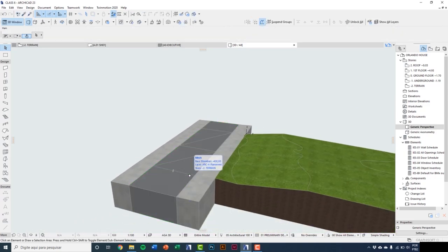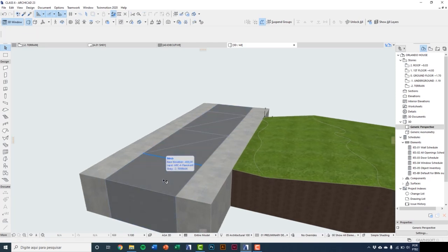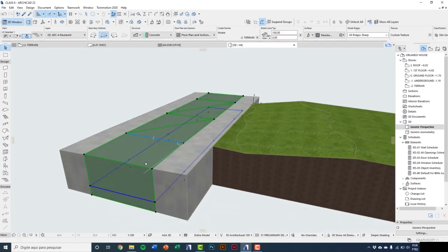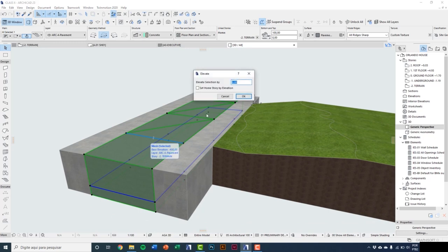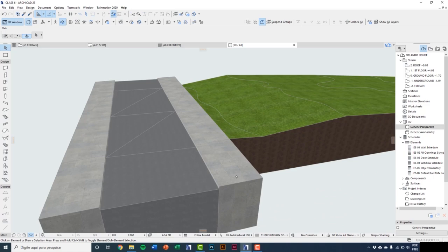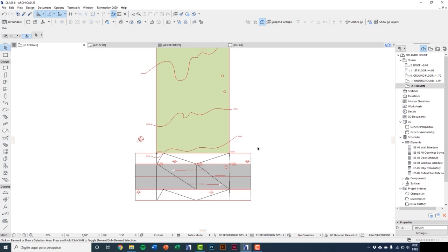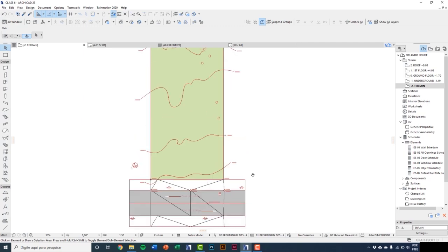Now, it needs to be 20 centimeters below the sidewalks. I select the mesh, use the shortcut Ctrl 9, type -20, okay. Therefore, the side context is ready. To finish, I will turn off the topographic layer and apply the ridge corrections as well.